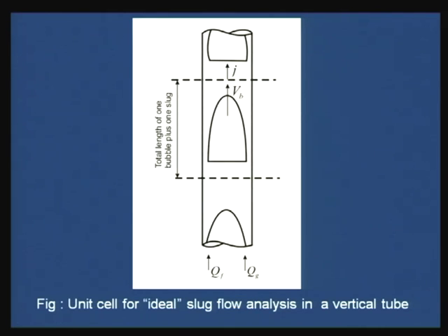But fortunately, we observe certain other things as well. What do we observe? We find that for most of these cases, the Taylor bubble can be approximated as a cylinder of constant cross section which has a constant curvature in the flow direction, isn't it? Also, the gas density and viscosity are negligible as compared to the liquid density and viscosity. Agreed? Therefore, the bubble surface can be assumed to be a surface of constant pressure. Therefore, the interfacial shear here can be neglected. So, interfacial shear part gone in the Taylor bubble region. What rest is remaining? Wall shear.